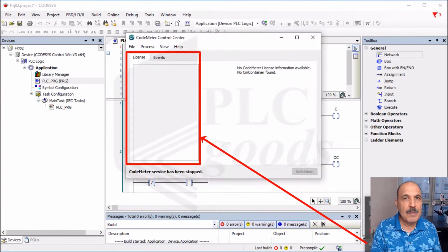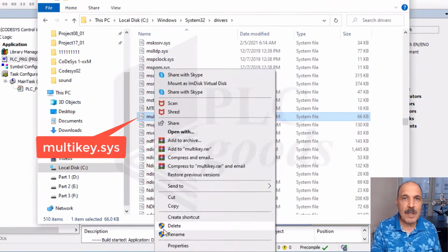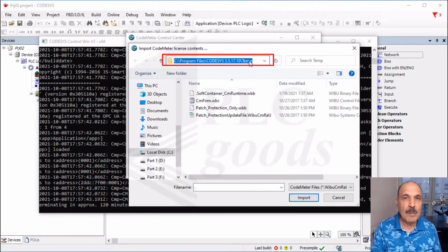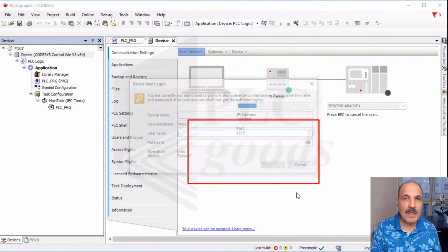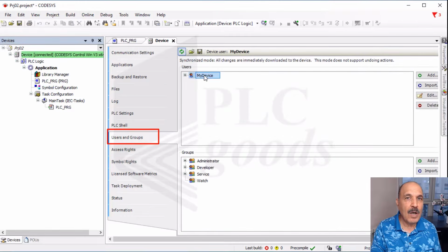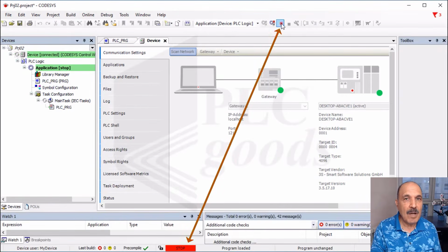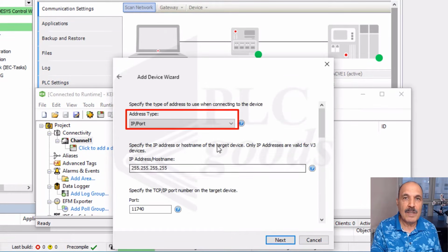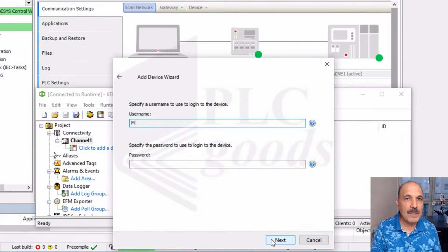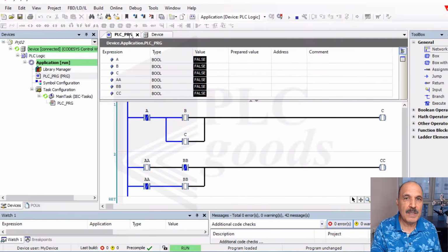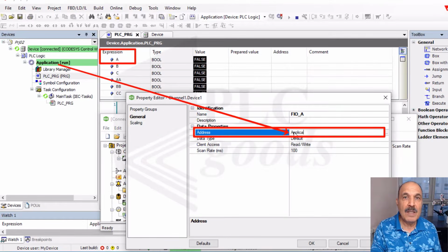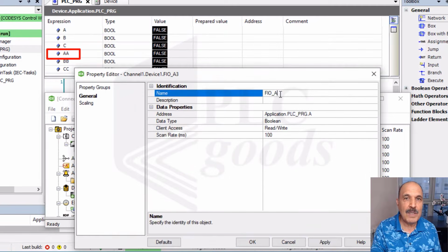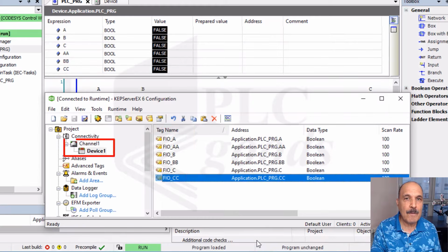In video lesson number 3, the tutorial shows the integration of CODESYS with Factory I/O using KEPServerEX software to simulate and control a basic industrial process. Viewers are encouraged to download the demo versions of both software for hands-on learning throughout the course. The steps involved in establishing the connection are outlined, including configuring symbols in CODESYS for sharing, creating a virtual PLC with CODESYS Control Win, resolving potential software conflicts, and connecting to an OPC server with KEPServerEX.